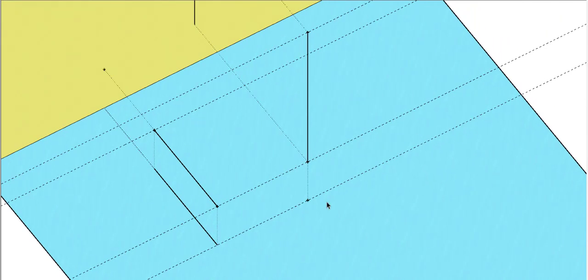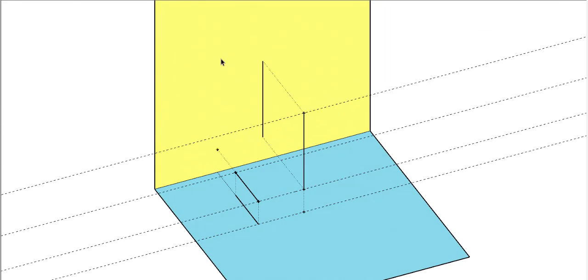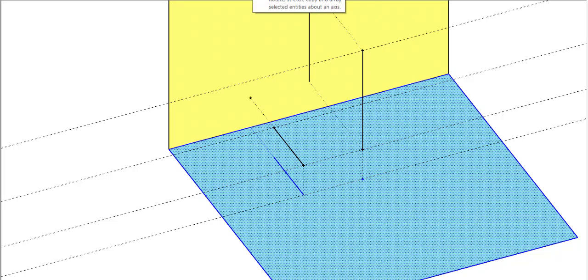So again, we project it downwards. While looking from the top, we project it downwards to the horizontal plane and we get a point here. While looking from the front, we project that entire line onto the vertical plane. So again, in order to get the orthographic projection, what are we going to do? We'll take the horizontal plane and take the projections and the projector, and we will rotate it in the clockwise direction by an angle of 90 degrees.